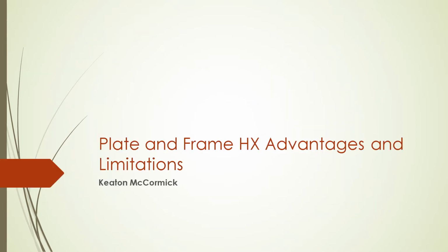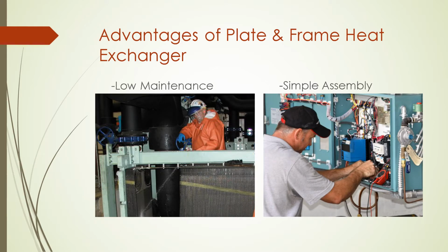I'm going to be talking about the advantages and limitations of the plate and frame heat exchanger. The advantages of the plate and frame heat exchanger include that it is easily maintained and simple to clean, and both of those are without having to take apart the configuration, and also it's more suitable for highly viscous materials. It's flexible, compact, and has close approach temperatures.